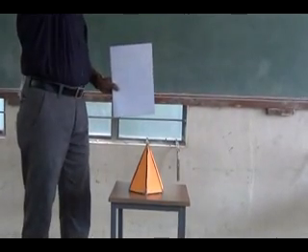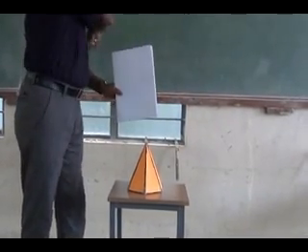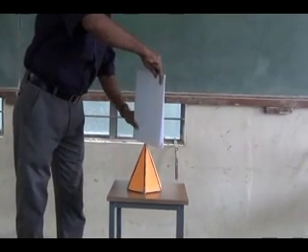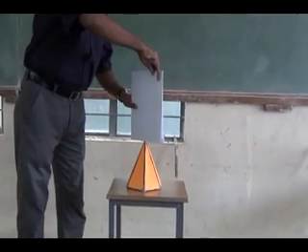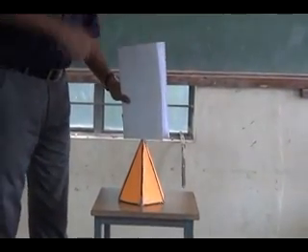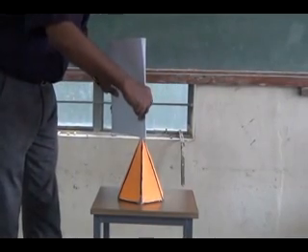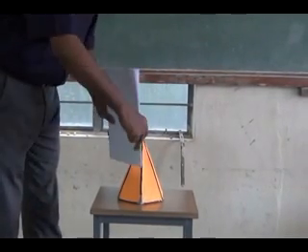What is the condition given? It is 40 degree inclined to VP. So it is going to be like this, 40 degree. It is not all the way in the, it is bisecting. How is it? Again 10 mm away from the axis. The axis is going to be in the middle. So from there 10 mm away it is going to cut.